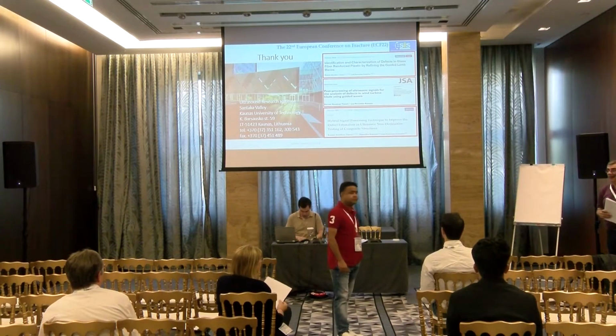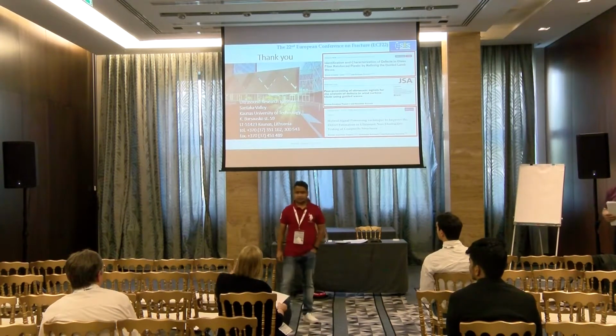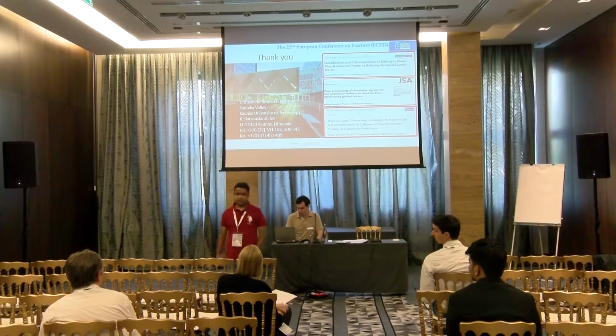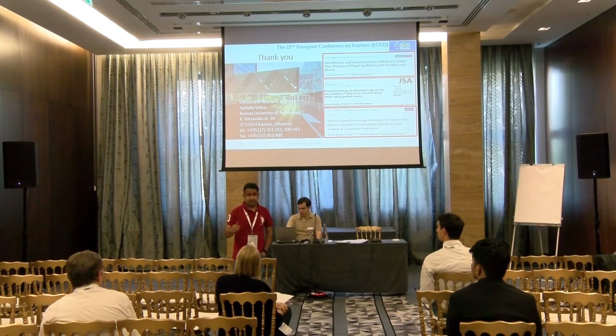Any questions, please? What precisely was the defect that you had? I don't know if I missed that. What kind of a defect? Did you have a delamination? Yes, it was disbonds. Disbonds created by the milling process, mechanical machining process. So you had a delamination, a separation between the layers and anywhere? Yes, anywhere in the thickness of the structure.